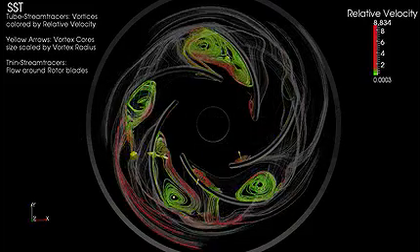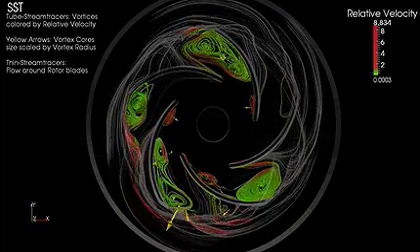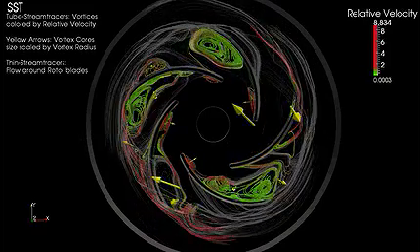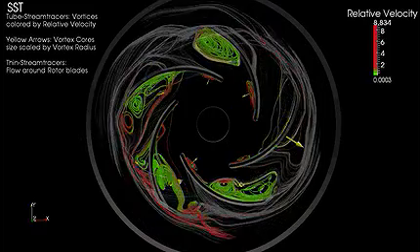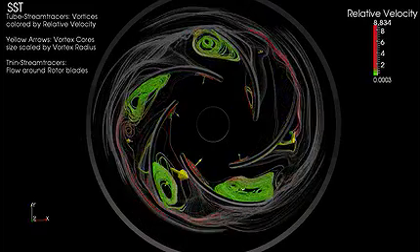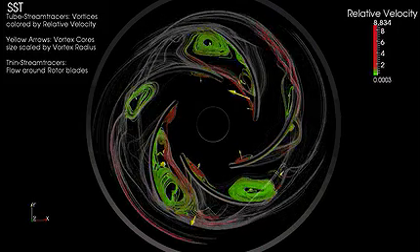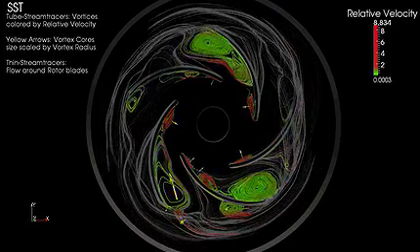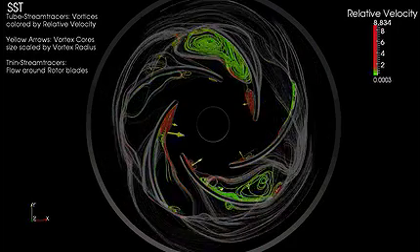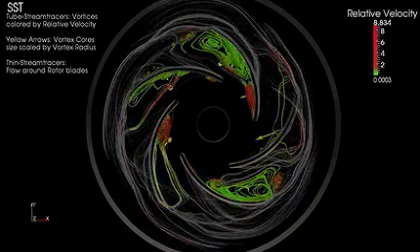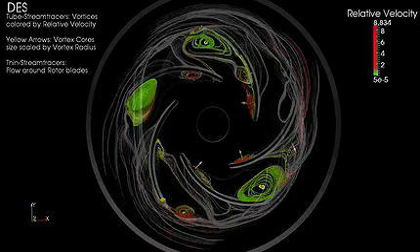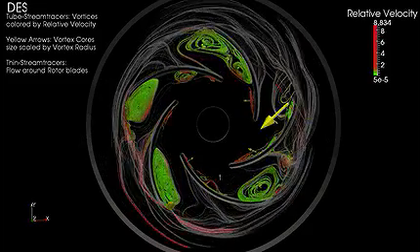To support comprehension of time-varying vortex behavior in a single simulation, we combined the display of streamlines seated at the rotor blades with display of algorithmically derived vortex cores. The paper describes the particular algorithm we used to locate vortices, but the technique will work with any vortex identification algorithm. We optimized the number of streamlines to enable a viewer using stereo to see through to both other streamlines and the vortex core identifiers while still being able to comprehend the overall flow.